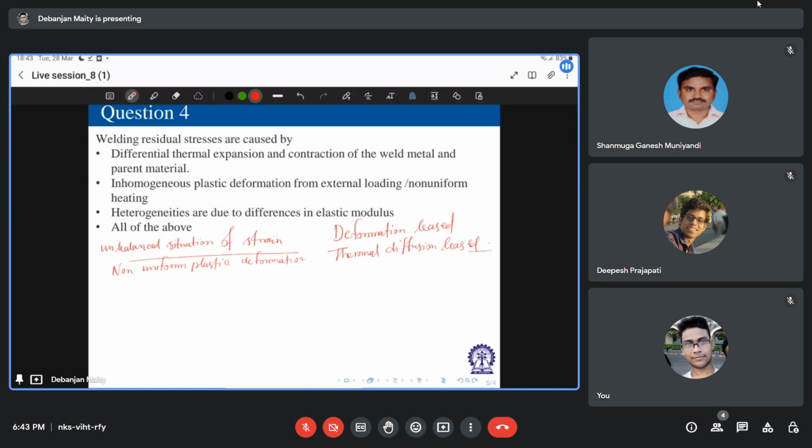In those processes, only heat is taking part in producing residual stress. In machining, for example, one source of residual stress is localized heating from the friction of the work done by the cutting tool and workpiece, right? Expansion and contraction associated with this heating and subsequent cooling is not free to take place because of the constraint imposed by surrounding material that has not been heated.